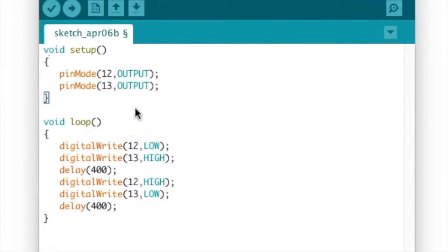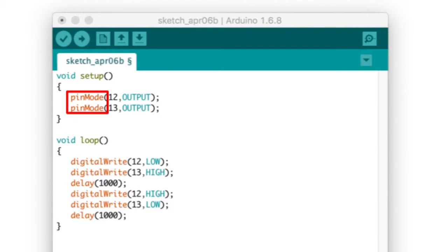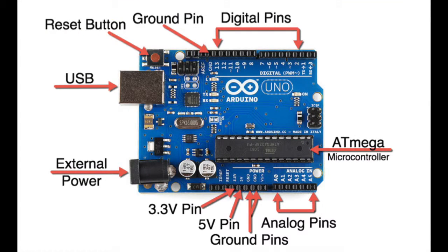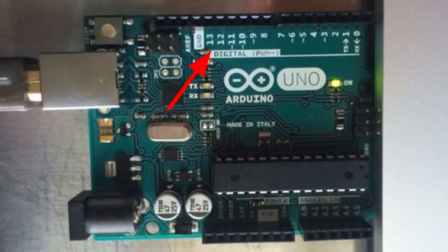The body of the void setup function has two statements in it. A statement is like a line of a poem and always ends with a semicolon. The two together form a bigger body statement. pinMode is another keyword. It is always followed by a thing in parentheses. That thing is a number, followed by a comma and defined as either an output or an input. What does pinMode do? It allows you to tap into the many pins of the Arduino board.